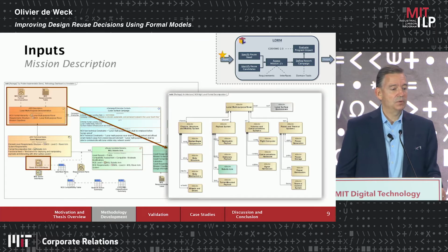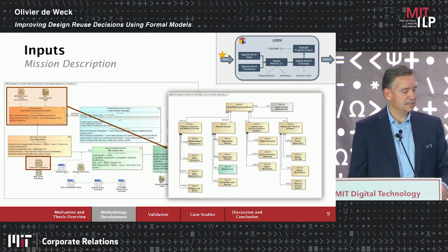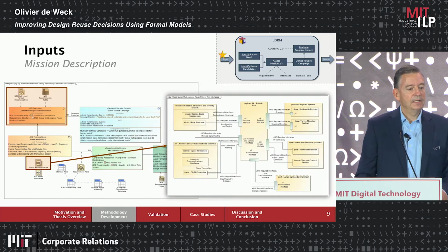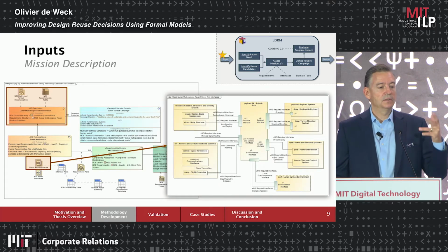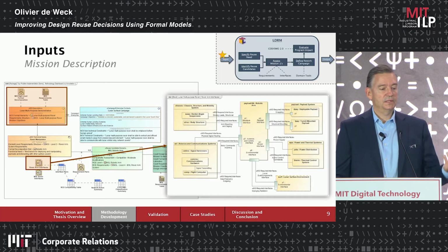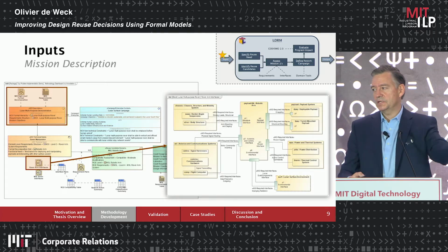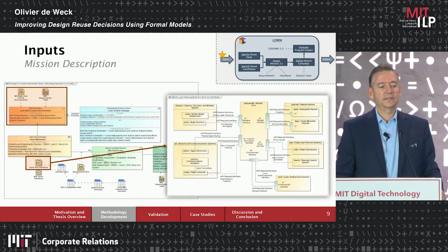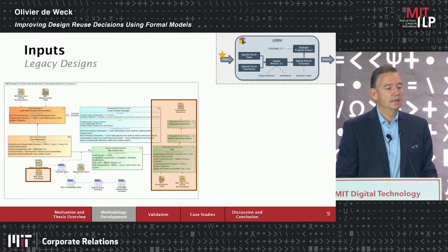How do you decompose the system into its subsystems? So you see the arm is that little green box there on the right. And if we zoom into that, what are the interfaces with the software, with the power system, with the control system, maybe thermal management? Do you need to heat the arm? Do you need to heat parts of the arm so your actuators don't freeze, during the lunar night? Those are the kind of things you have to think about.